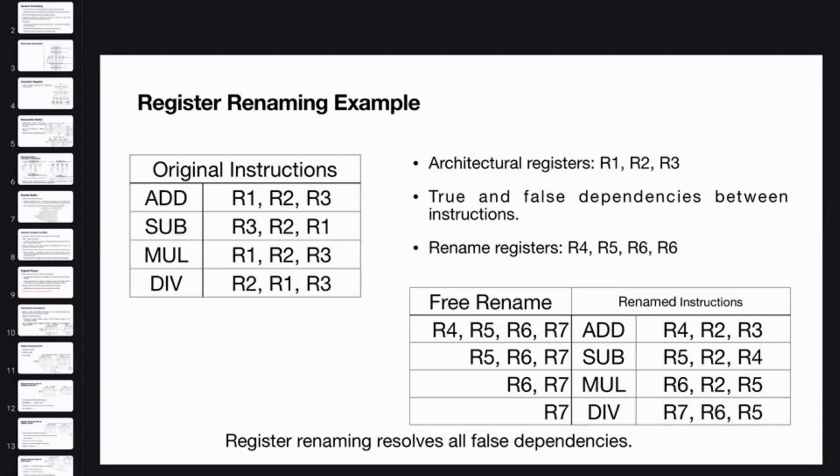That is the reason Intel microarchitecture is different from AMD microarchitecture, for example in the cache hierarchy. One may consider a 3-level cache, with L1 and L2 private and L3 shared. An AMD architecture may consider L1 private but L2 shared by 2 cores within a single multi-core system. Or they can consider different types of caches, inclusive, exclusive, non-inclusive, and different designs. All these depend on the behavior they get with the scientific applications, and based on that they go ahead.